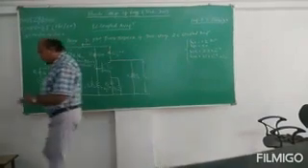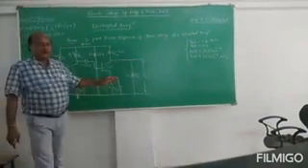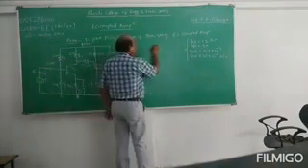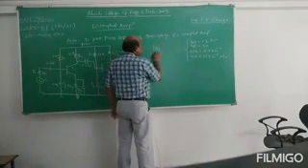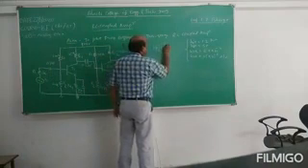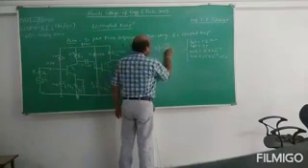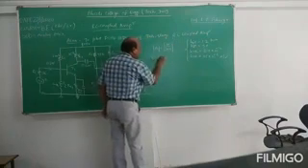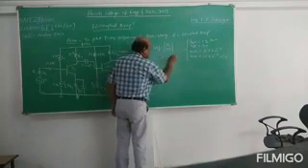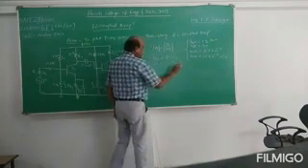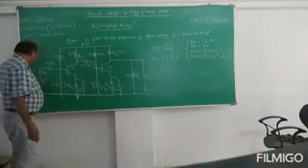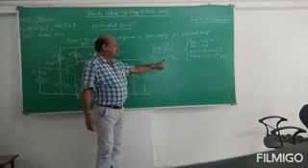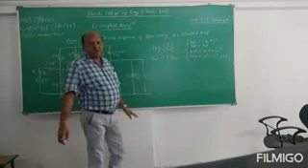Then what we have to do for the practical purpose is calculate the magnitude of the gain. That magnitude of the gain is nothing but magnitude of output upon magnitude of input. And this input is fixed. The amplitude is fixed, let us say 0.5 volt peak to peak. We will keep this input V in, its amplitude of 0.5 volt peak to peak, fixed.